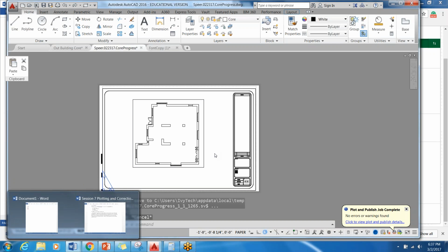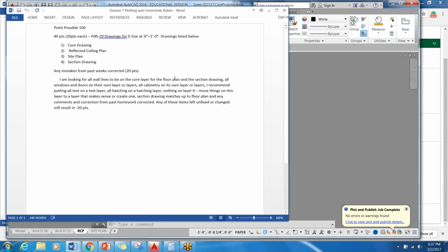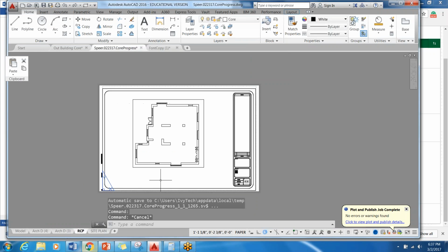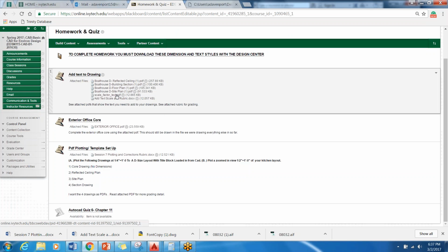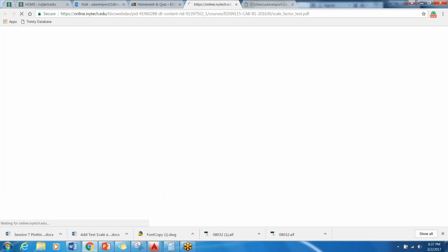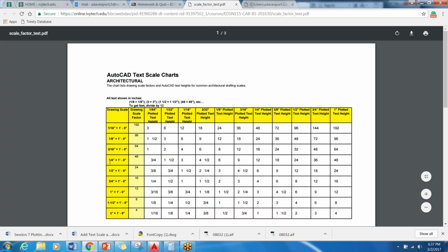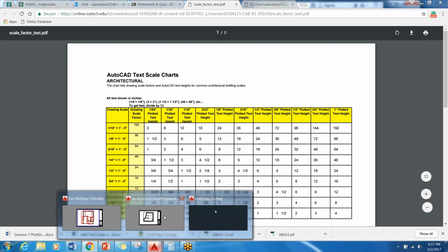You're going to make a sheet, and then you're going to follow the instructions of how to do the text height. Or, and I guess that's the only other nuance, if you don't want to do it annotatively for the text height, you need to come into the scale factor, and wherever I'm saying at a 1/4 inch scale, it's going to be 1/8 inch. In your model space, instead you're going to type it in model space at 6. Does that make sense?